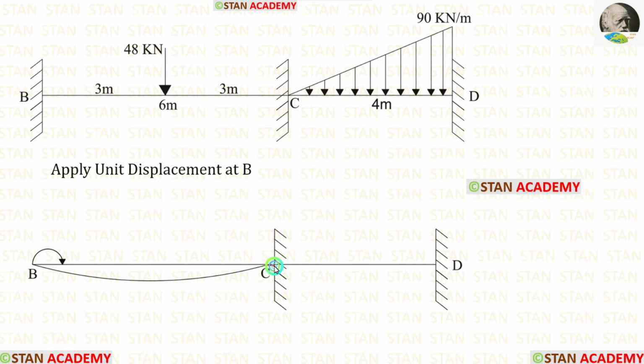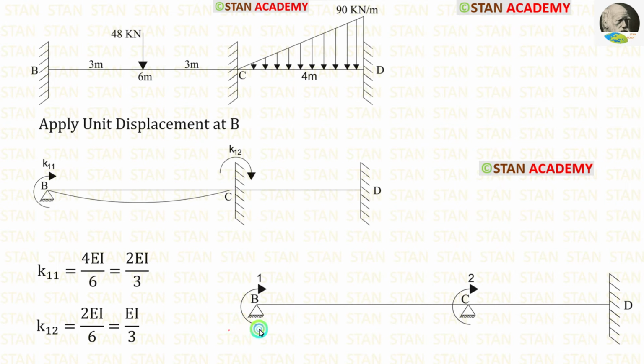You can see that I have given some gap between the fixed support and the curve because in the fixed support there will be no slope. That is why the curve ends before point C and it cannot continue after point C. Same as here, the ordinates should be made in the clockwise direction.